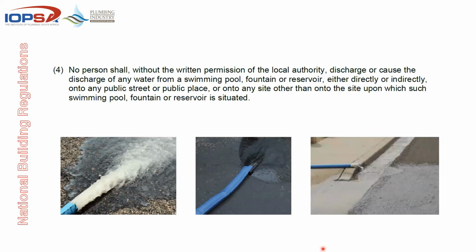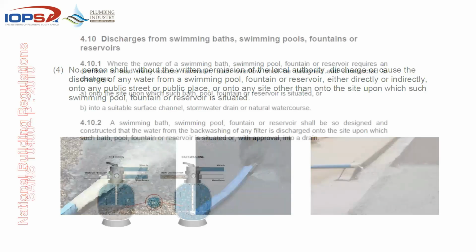Obviously, the chlorine damages the tarmac in the road surface. You have little bits of water causing havoc, with the water that ends up running down the curb or through these little channels here, ending up in a stormwater, but it's not enough water to actually run away. So you have little pockets of water in the sumps and catch pits with that chlorine in it, and it ends up becoming a problem. So you can say that, having been told that you can't have that running onto the street, the solution to that problem is actually very simple.